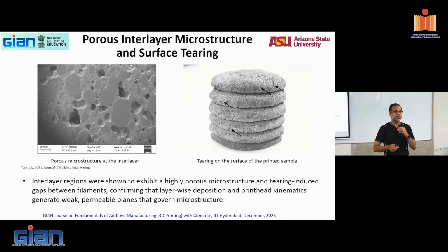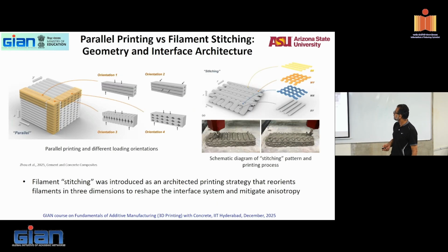There is actually a company which, along with a nozzle, comes with a side attachment that finishes the brick as it lays along. So you can do that, but then you need a very good flowable mix for that. And once you make it more flowable, you have much more propensity for interface effects and all of that. So again, it doesn't come without disadvantages.